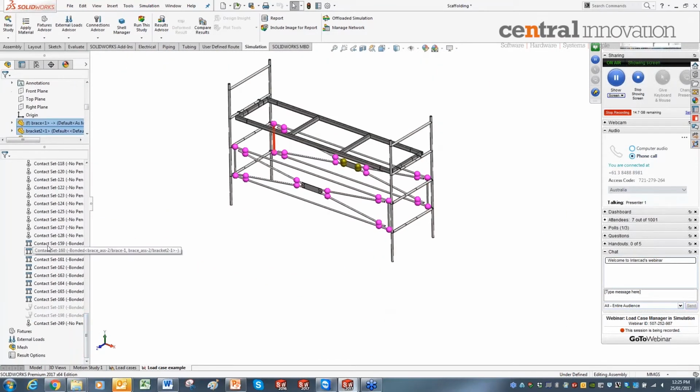Okay, and then the rest of them are the bonded conditions between the beam and solid elements. So all the contact sets are defined. The next step is I have to define the fixtures. Like I mentioned in the slide, this load case manager can be used to manage your fixture definition also. If I define like 4 fixtures, I can toggle on and off selected fixtures inside the load case manager. I'll show that later. First thing is I have to define the fixture definition.